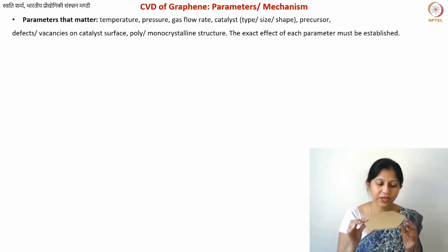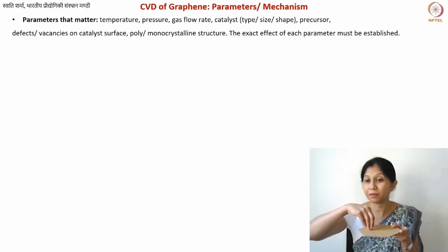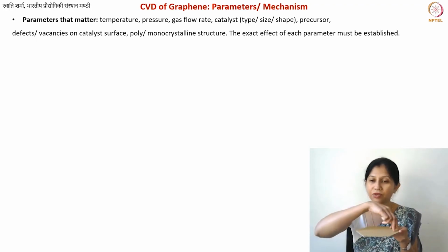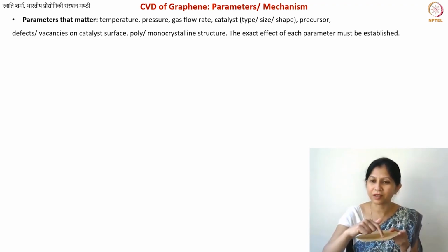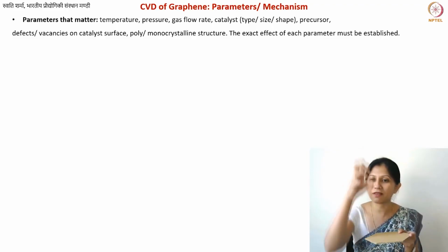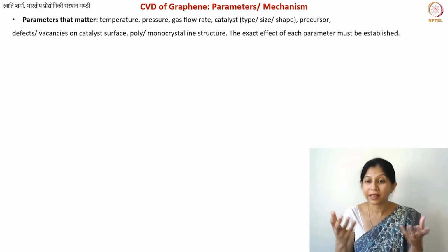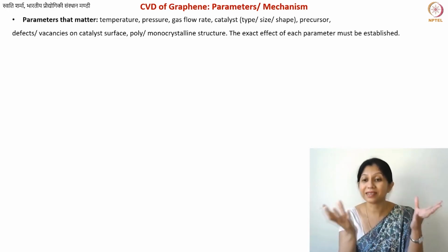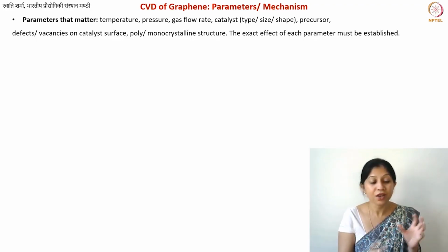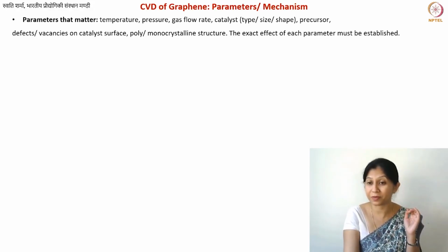Okay, now if your substrate has vacancies, so now let's say you have this carbon species here, and then it migrates through your entire substrate. Wherever it finds the right place to sit, if there is a vacancy, if there's a defect, that's where your carbon will go and sit. If the vacancy size or the defect size is large enough that multiple carbon atoms or species can sit there, then they will all go there, and then that will definitely nucleate something. Your film might nucleate from there. So you may or may not want that kind of behavior from your carbon species.